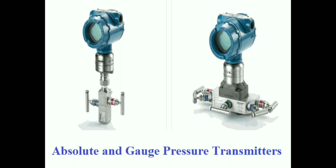Reference pressure. An absolute pressure transmitter references pressure to absolute zero, or vacuum. In a gauge pressure transmitter, the reference pressure is atmospheric pressure. Zero reference. In an absolute pressure transmitter, zero is at absolute zero pressure, a vacuum. In a gauge pressure transmitter, zero is at atmospheric pressure.